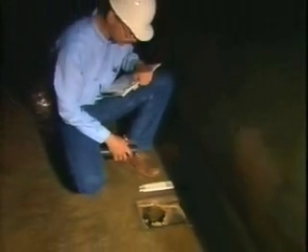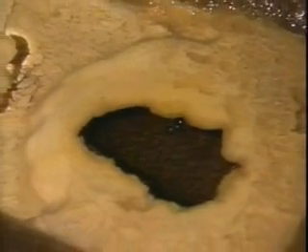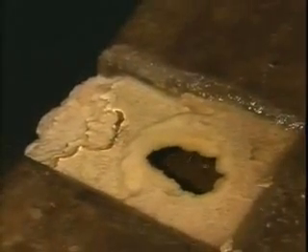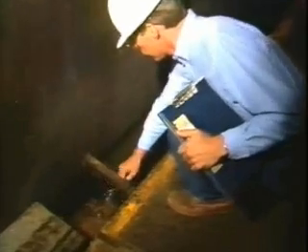Another feature to check when inspecting the interior is the foundation drains. These drains help relieve uplift pressure beneath the dam. Check to see that the drains are not clogged with chemical deposits, either visually or by sounding and probing. A progressive decrease in the volume of water flowing through the gallery gutters may be one indication of clogged drains. Visually inspect the drains and determine the flow rates at gutter weirs. Compare the results with previous reports.